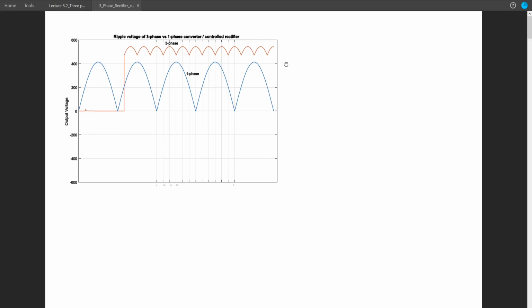And again, we are getting a higher voltage in case of a three-phase, since the three-phase voltage is √3 times the single-phase voltage. So it is always preferable to use a three-phase system if our system permits, as the energy density of three-phase system is much greater than a single-phase system. But surely this three-phase system is more complicated than a single-phase system. So in case of an industrial application, a three-phase rectifier system is always preferable. In case of household application, we usually use single-phase system.